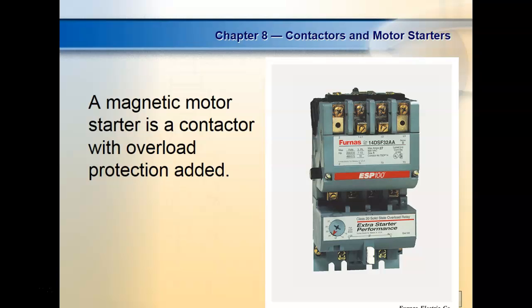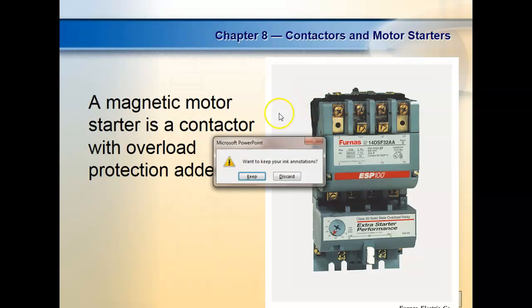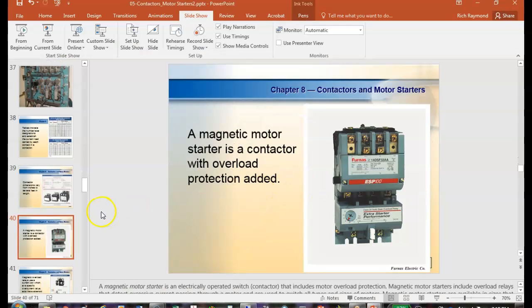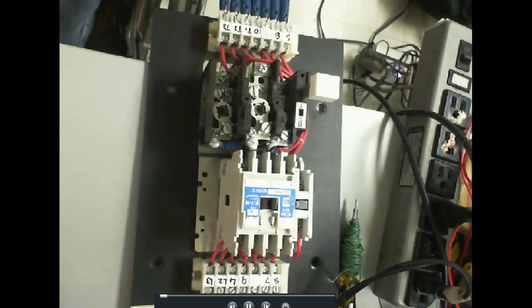And like I said, usually you can buy the contactor separate. So normally what the company does is they'll have a metal plate and they'll mount the contactor on it, and then they'll mount the overload on it, and then they'll wire that contact in there. So that little short wire that we see, you don't access that. That's done when they add that overload. So we see when we wire this up, when we do our wire numbers, wire 9. So let me bring my camera back up. See if we can see the actual wiring.